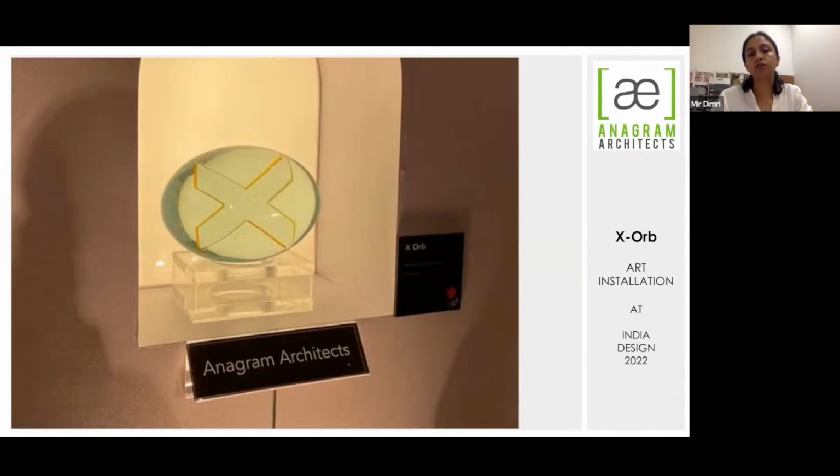So over here, it's a curious shape, but what we've done is taken thick slabs of glass and cut them into an incremental profile, such that when you place those different slabs one on top of the other, and you stick them and you grind the round around it, this is what you get. So the X that you see in the center is actually a cutout that is stenciled out from the middle two slabs of glass, and then you incrementally add glass on top of the other. In this picture it seems like it's molded glass, but what it really is, is slices of glass that were stuck together and then sanded all around to get this really smooth space.